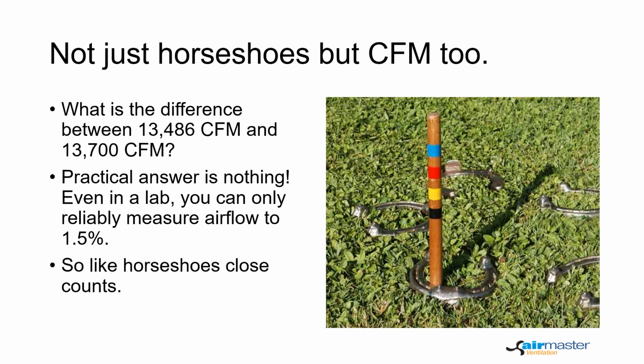In a lab, you might be able to measure within 1 or 2% of a true value, but in the real world, in a plant, and with large amounts of turbulence, you would be lucky to get within 5% and more likely within 10. And the fact is, by the time you were even partway through the measurement, the conditions would change.